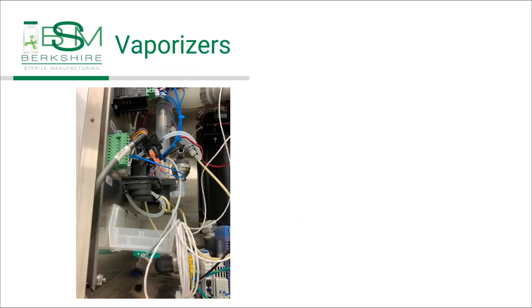I'm going to show you a couple of examples of vaporizers here. This is from a Steris M10 unit. This is really very simple, even though there's a little bit of electronics. It makes it look a little more complicated than it is. This is essentially just a graduated cylinder back here that fills up with liquid hydrogen peroxide at the beginning of the cycle. And then that liquid hydrogen peroxide is pumped by a small peristaltic pump, which is right here. You can see this is the line coming into the peristaltic pump, and this is the line going out.